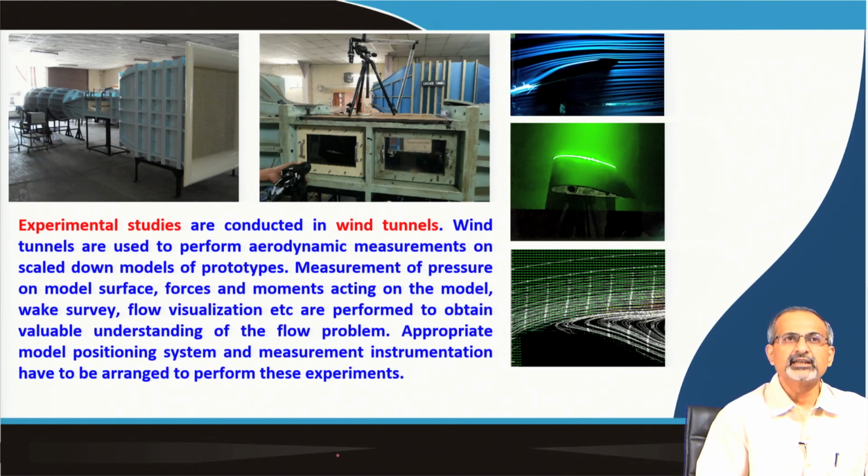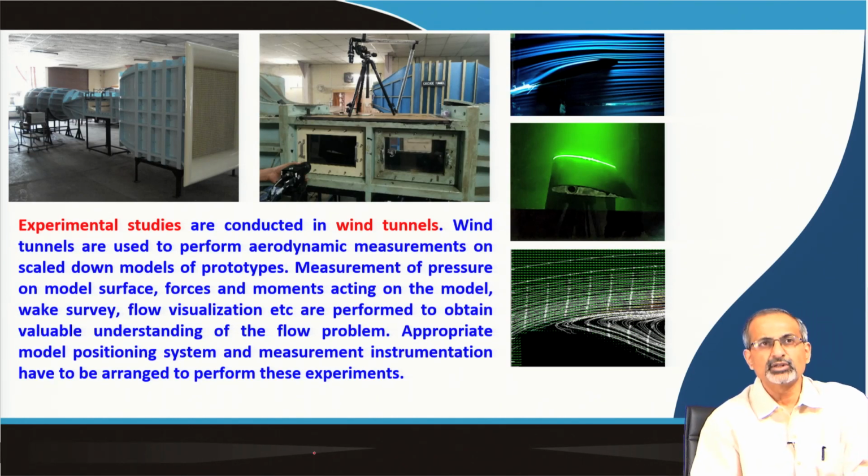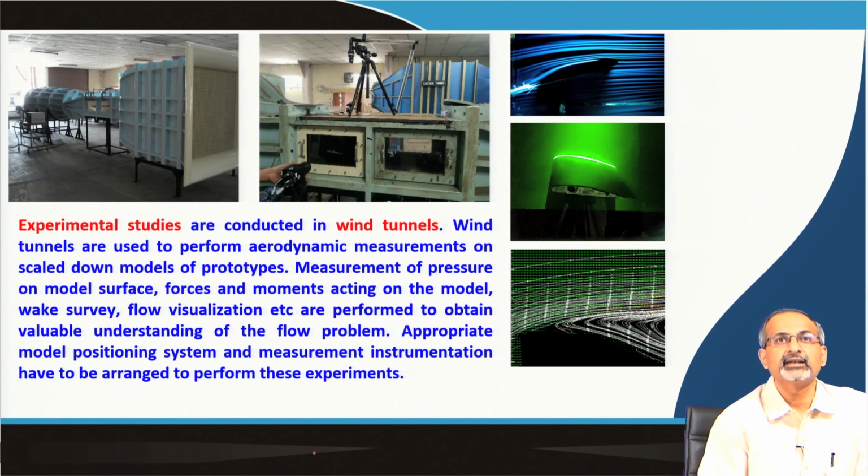In that initial lecture we had talked about experimental studies being conducted in wind tunnels, and wind tunnels are used for aerodynamic measurements, where we measure pressure on model surfaces, forces and moments acting on models, we do wake surveys, we do flow visualization, etc., so that we attain valuable understanding of the flow problem.